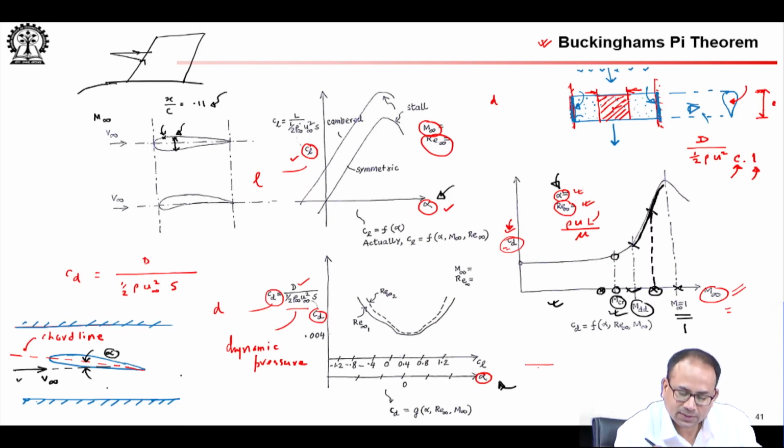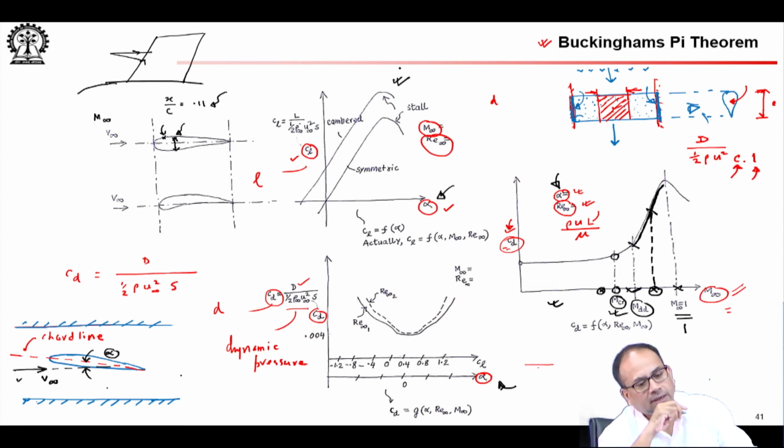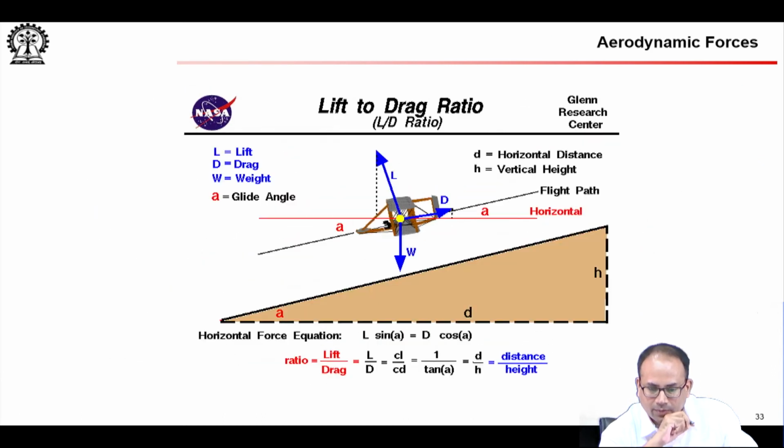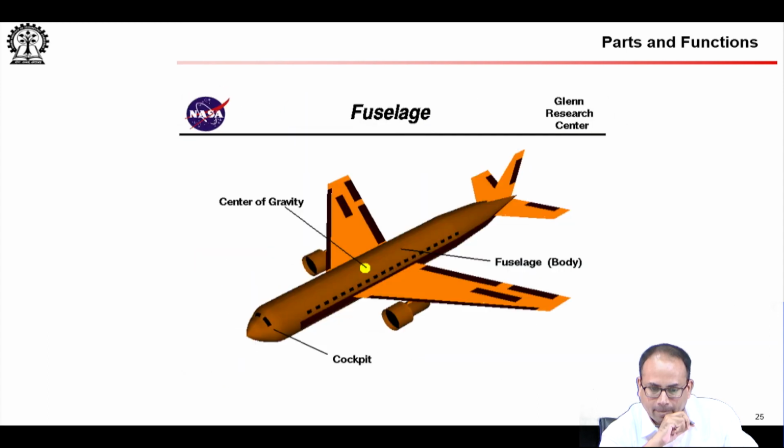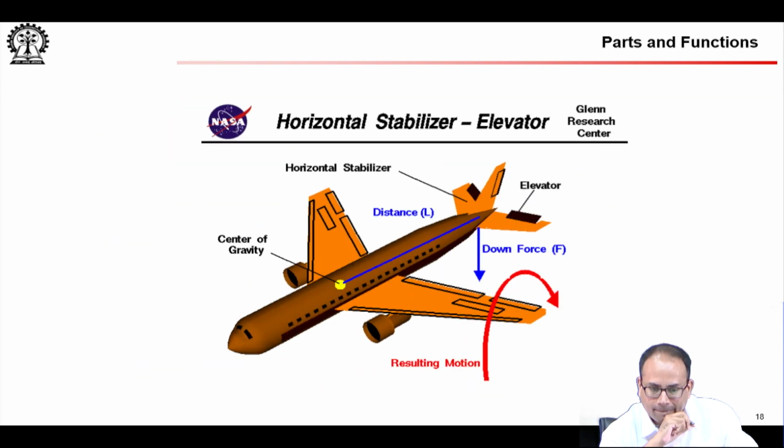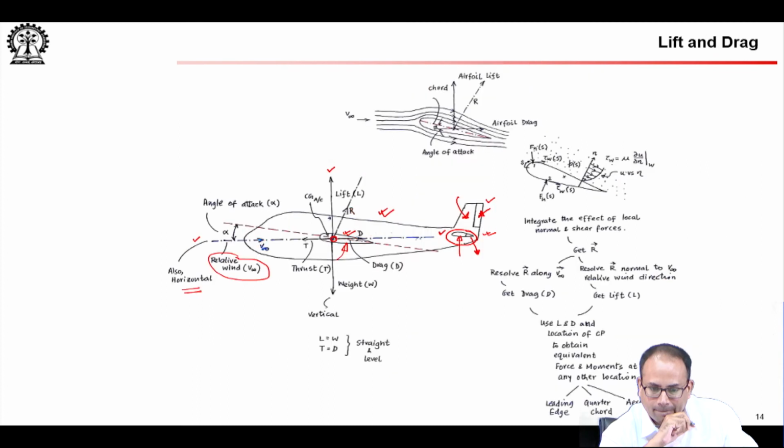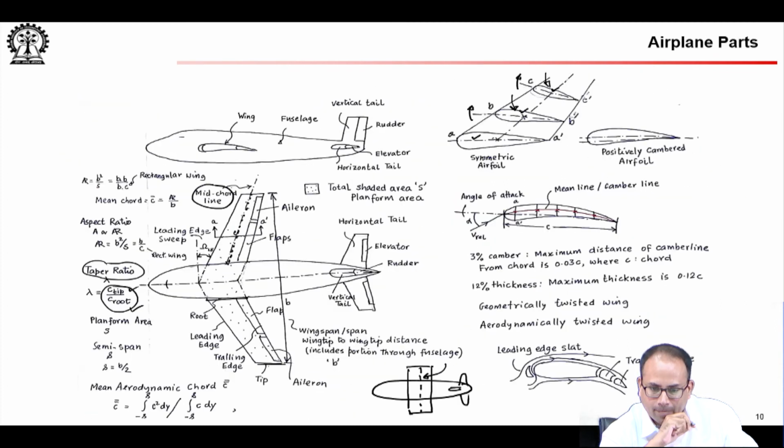If you look at these, you see that when you deflect the flap, okay, hold on, what are we talking about here? So, when you have different airfoil cross sections, what can happen is the alpha at which you have 0 lift can change from section to section.